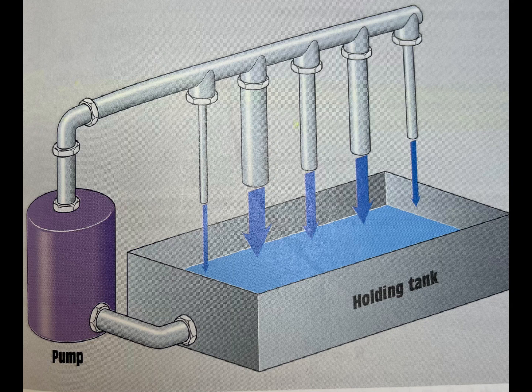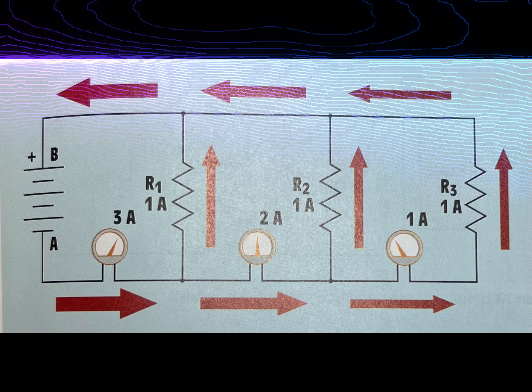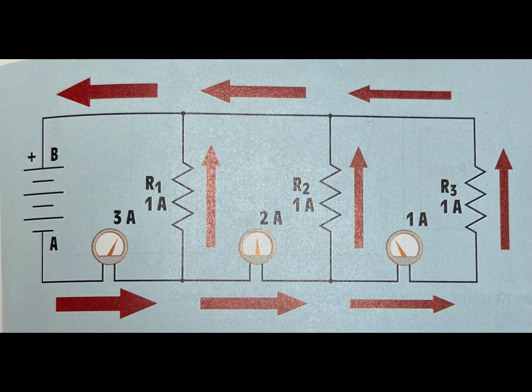That concept often causes confusion concerning the definition of load among students of electricity. Students often think that an increase of resistance constitutes an increase of load. An increase of current, not resistance, results in an increase of load.